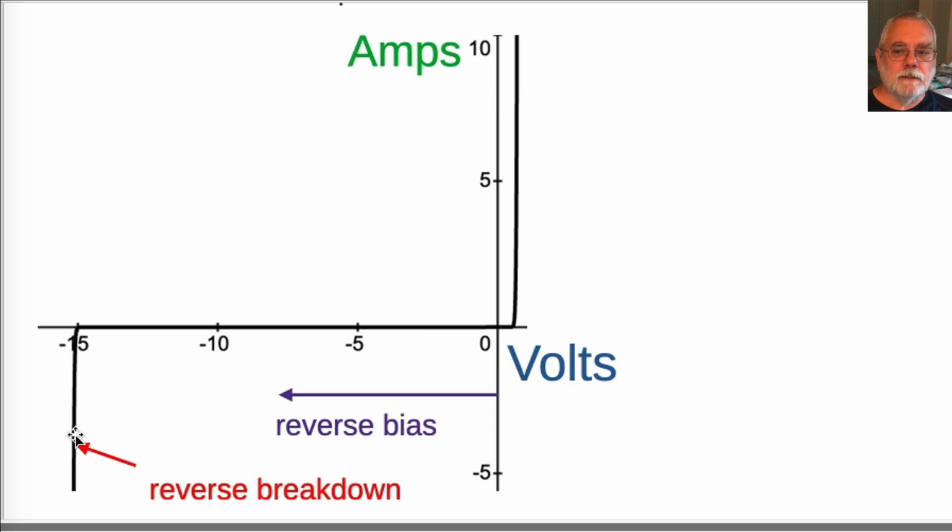It doesn't seem like solar cell specification sheets generally tell you their breakdown voltage. Reverse breakdown does not seem to be the reason why partially shaded solar cells get hot. Details of the breakdown current voltage relationship won't matter for this video, but the breakdown voltage impacts the discussion. The solar cell may also have some shunt resistance such that the reverse bias region current has some slope to it. This won't change the discussion in this video.